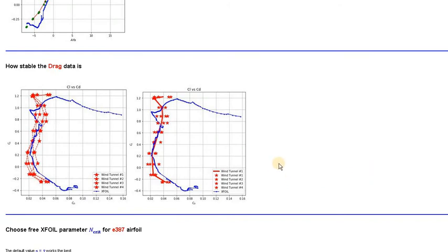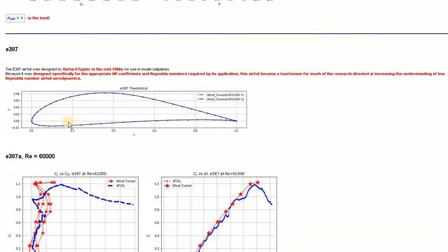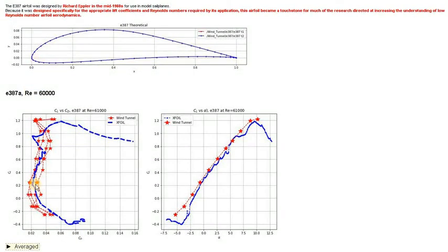So the next step is to compare those airfoils. To compare them, we have to know how to compare them. For instance, we have to know the lift coefficient, because the lift coefficient may vary, but it depends on the speed and the mass of the plane. For instance, if you go fast and you have a certain weight of the plane, you don't need a huge lift coefficient. You might need just 0.1, maybe. It depends on the speed of the plane. So all those parameters are known.